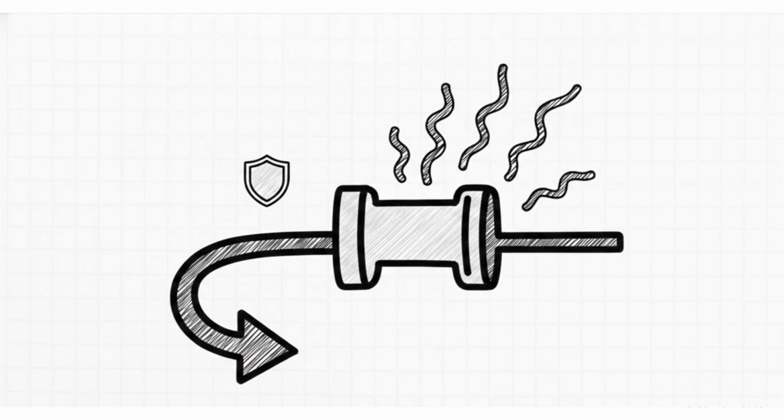But, you know, there's a catch here, and it brilliantly illustrates a major real-world engineering challenge: power dissipation. See, when current flows through a resistor, that opposed energy doesn't just magically vanish. No, it converts directly into heat. Using the formula power equals current squared times resistance, we can actually calculate this. So if you're dropping 5 volts across a resistor carrying 20 milliamps for an LED, that little guy is generating 0.1 watts of heat. It has to safely absorb and dissipate that heat, otherwise, it's literally going to burn out right there on your board.